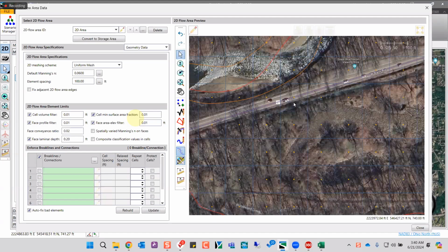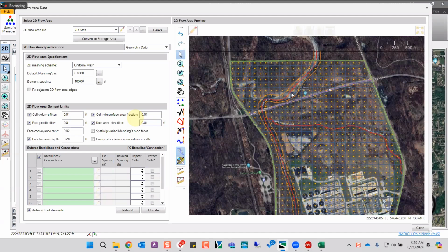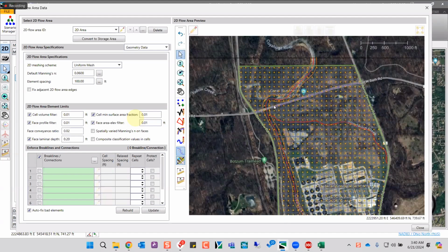and the computation of the cell is handled at the cell center point. But the problem with this approach right here is that you can have water coming in from one side of the cell and magically appear on the other side when it is physically not possible due to this elevated roadway crossing which you have in between. But the software wouldn't know that. So this is where the concept of break lines come into picture.